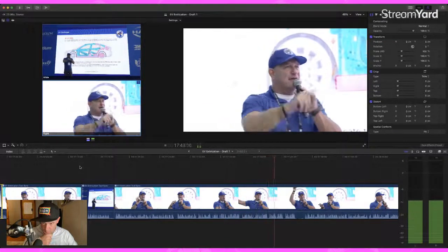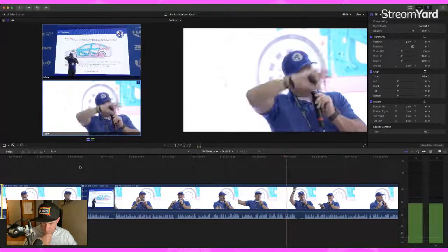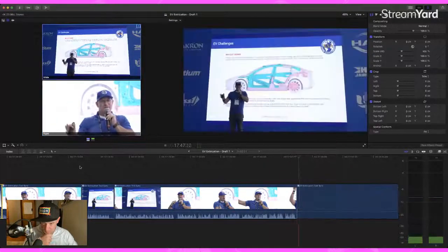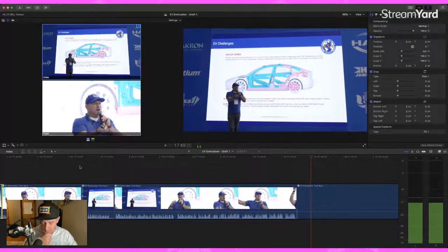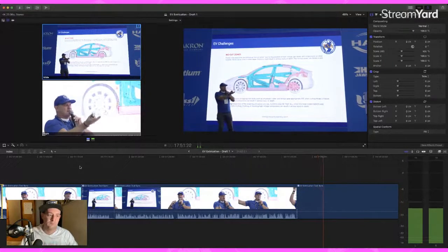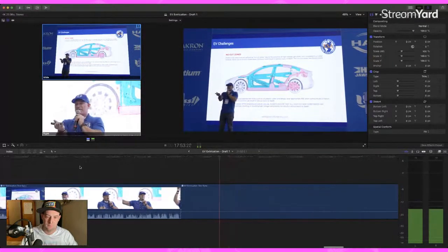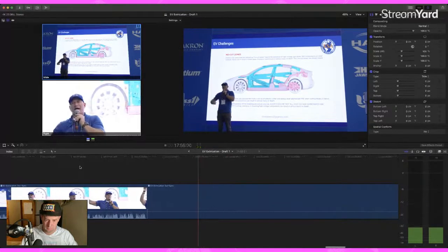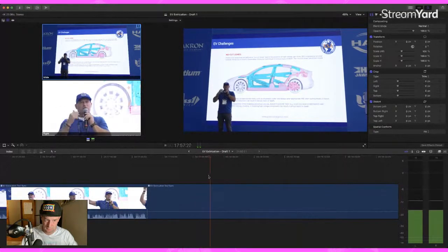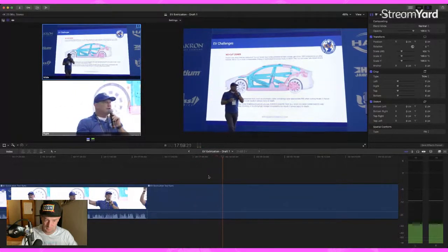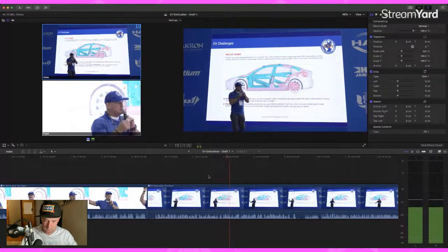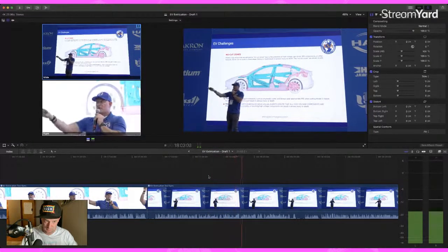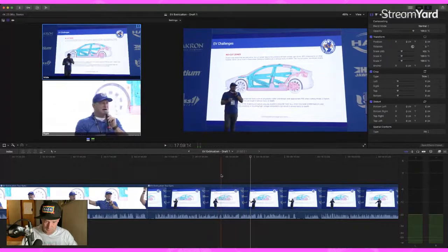Your big indicator is cherry bubble gum. Everybody say cherry bubble gum. That's an odorant smell connected to the solvent within the electrolyte of lithium-ion batteries. Tesla coined that term. I just say it's an electrical odor that's really, really sweet, okay? You'll always know it once you smell it.